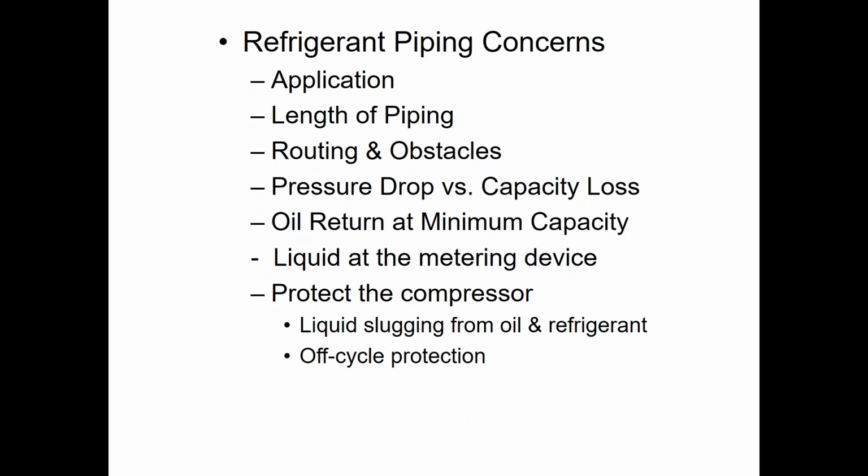As I think everybody knows, there are 2 reasons for refrigerant piping. One, to handle the movement of refrigerant between the various components, the coils, the compressor, and whatnot. But two, in sizing, to also aid in returning the oil back to the compressor. Every second that compressor is on, there is a little bit of oil leaving the compressor, entrained with the vapor, coming all the way back to the compressor again.